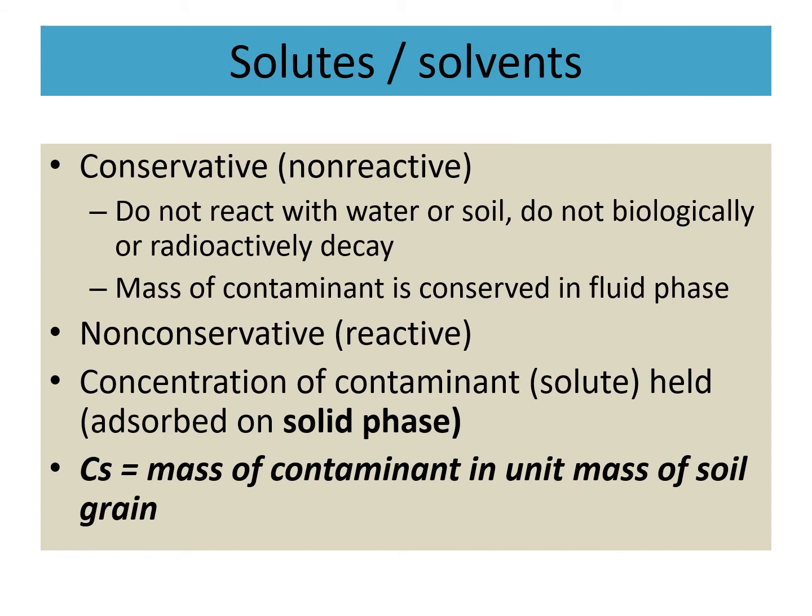But if it is reactive, if it is getting dissolved in water, if it is getting reacted with some other minerals or ionic conditions, ionic radicals, in that case it will be changing its formation and it will then be mixing with the aqueous phase of water, and then it will behave as a solution, and that solution will move based on the geological structure and formations. But the adsorbed portion is going to be retained within the soil. It is not going to move forward.